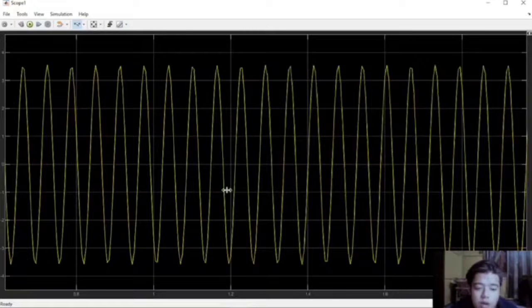When we compare the waveform of the decoded signal for 4-bit and 8-bit PCM data, we can see that the 8-bit decoded waveform has a greater amplitude than the 4-bit decoded waveform. We can conclude that the more bits encoded in PCM data, the closer the final signal waveform is to the input signal waveform, as it maintains a higher amplitude. So that's all for part A.